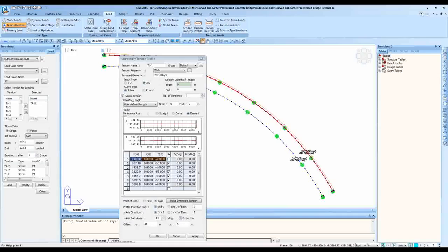And you can actually just increase the number of tendons. So with one typical profile, just increase the number so that the program can consider 5 times the effect of a single tendon. That way, if you're not really set with your tendon data yet, you can do basic, approximate tests with this typical tendon function.